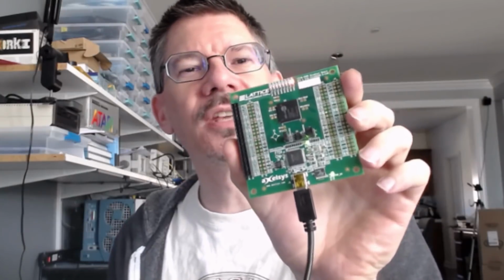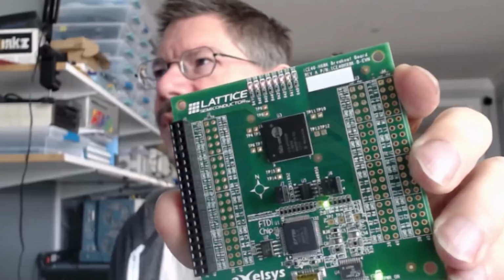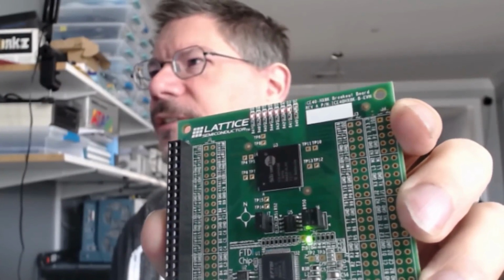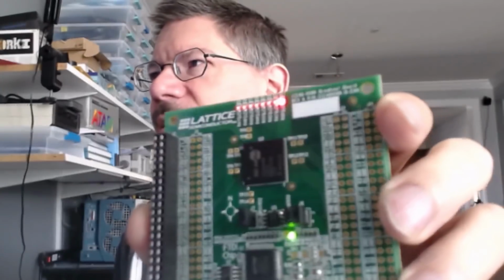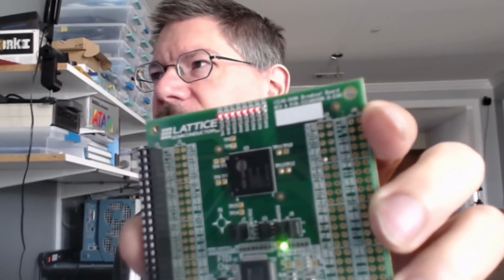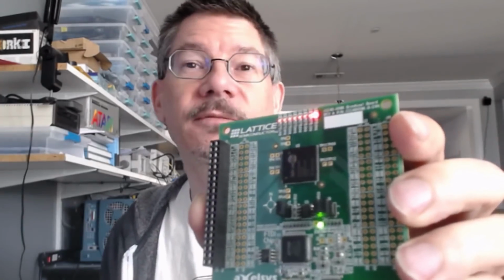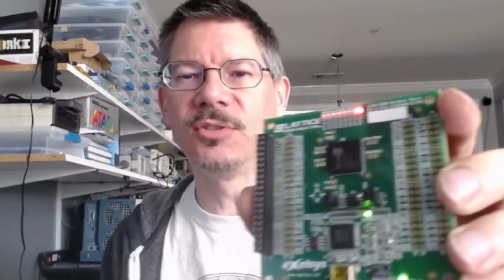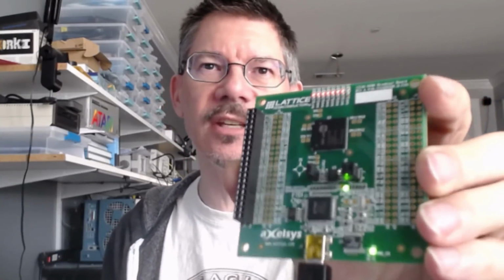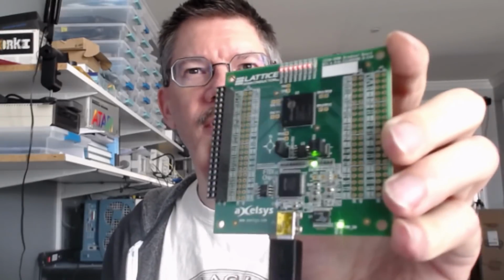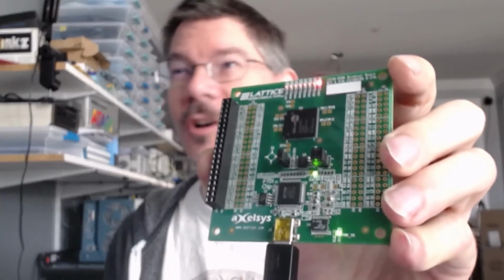Now, the other interesting thing is that we can see that one of the LEDs is blinking, but if I bring it in a little closer, you can see that the other LEDs are actually lit dimly. And I think that this is probably because we didn't actually set the level for those LEDs. So it's just sort of floating there or something. So presumably we could change our program to actually zero out those LEDs, and hopefully that should make the LEDs go off.